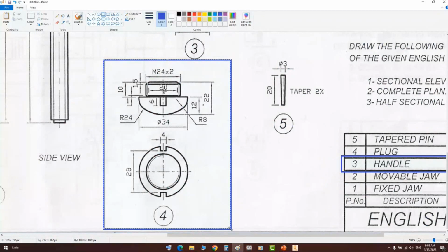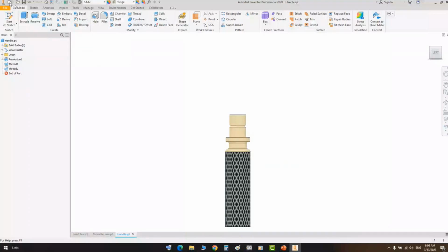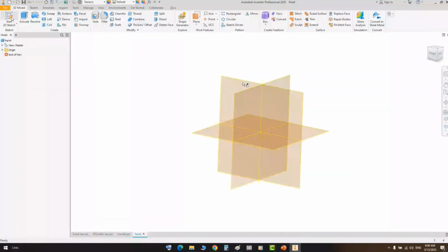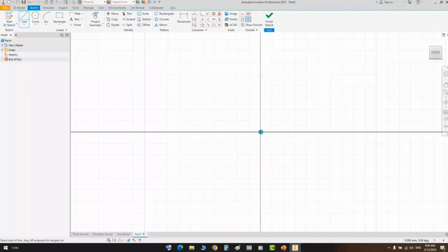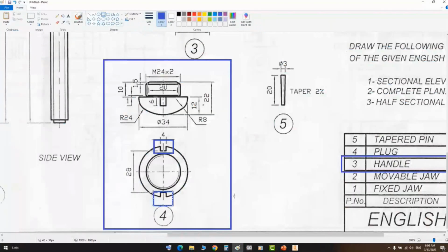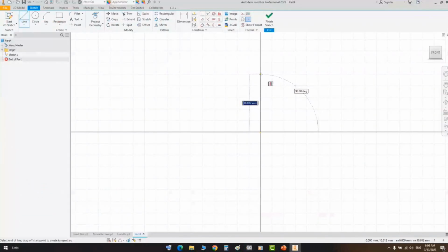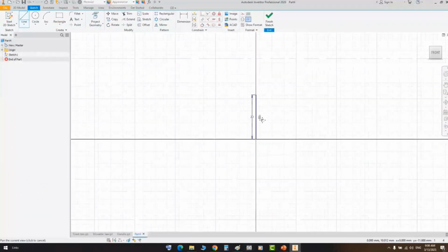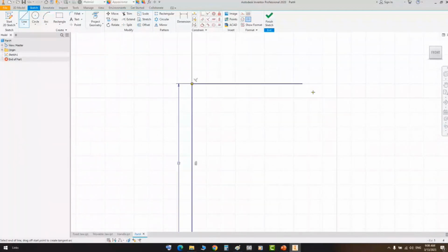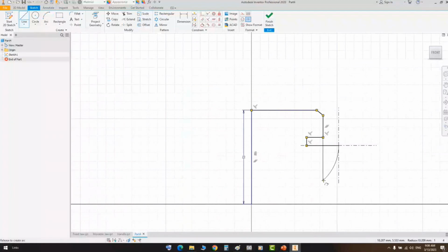It's the same. We have to make a revolve for a section. After that, we have 2 small cuts here and there. But the main feature we can create by using revolve. So from here, let's create a new standard part, and from here select this one, and here define the height. So the height of this one is 22. From here, let's define the height as 22 millimeters. Draw the section. We have a chamfer here, another sharp edge, and that's the contour of this one. By drag and move, you can make an arc, and the same another arc up to here.